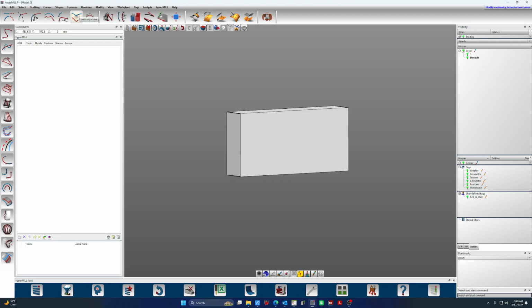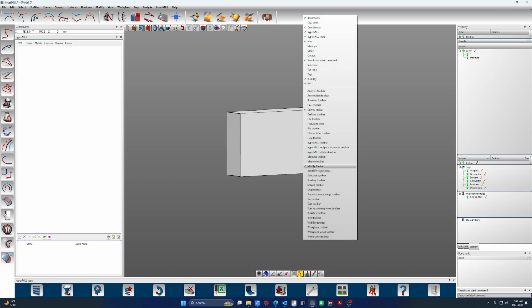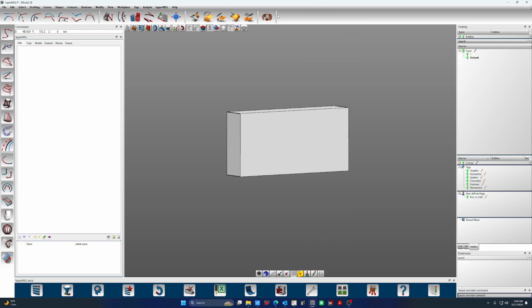Continuity curve, basically taking curves and blending them together with parameters. Modify control points. If you have a shape or curve that's obviously not geometric, when it was created with a number of these control points, maybe in the foreground, maybe in the background, depending on what tool was used to create it, this sort of highlights those control points and lets you drag them around. All those points are weighted, and depending on how you move them, changes the way the curve looks. So that's the modify toolbar. We're going to leave the modify toolbar active because the modify toolbar is awesome.